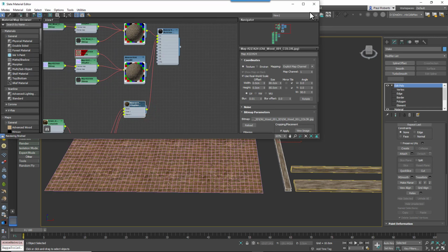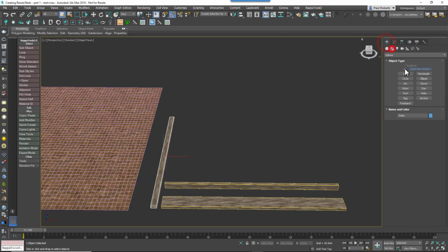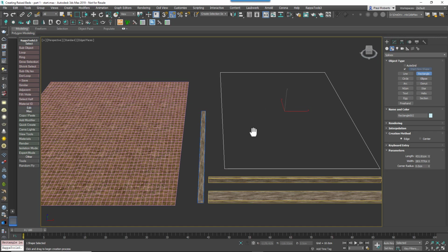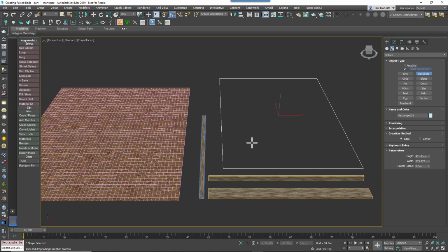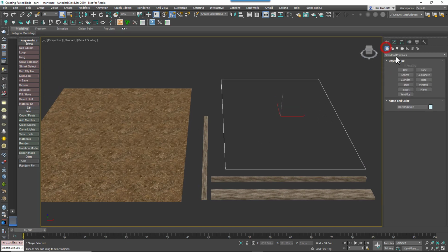And that's it. Both RailClone and Forest Pack are going to use the same spline, and to build the style we'll just use a simple rectangle. But you're not limited to these basic shapes, the beds can be more or less any shape you like. And so now with our geometry and paths prepared, it's time to jump in and create the style.